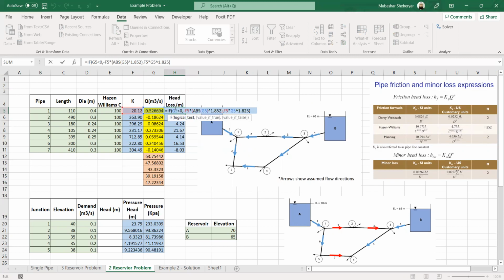So I just apply the condition that I have assumed the flow through each pipe. I want to know whether I am assuming the right direction, therefore by applying this condition, I will find the actual flow direction in each pipe. The other point is that when we apply the exponent of 1.852, it doesn't give us a proper value for each equation. It gives us a different value. Therefore, I am applying the condition by applying the absolute function as well.